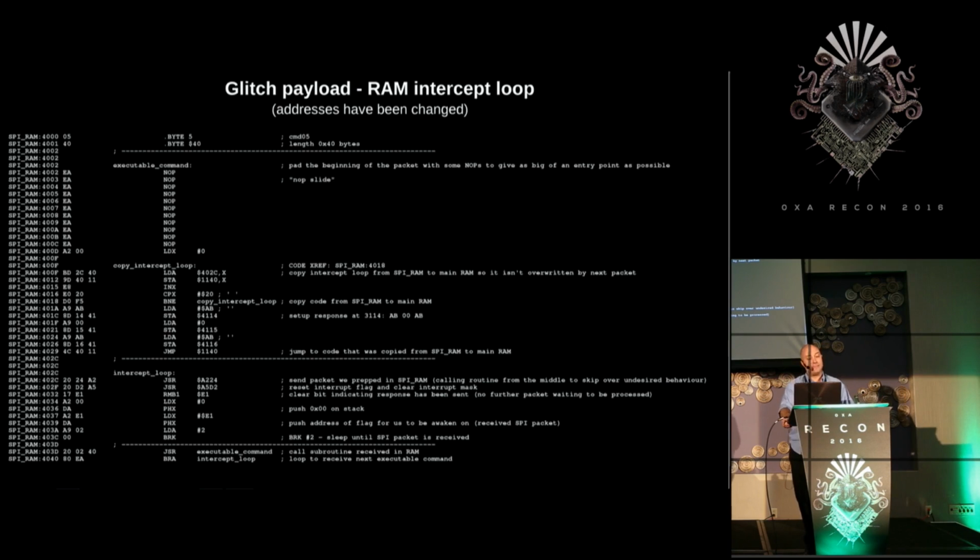Now my goal is to have the ACP execute the code of my choice. Because the 6502 is a von Neumann architecture, all the code and data memories share the same address space. From the software disassembly, I've seen that there doesn't appear to be any kind of paging or MMU features. The software in the ROM is fully self-contained. There is no EEPROM, and the RAM is never used to hold executable code. So there's no jumps into these areas to exploit, and it wasn't really clear at this time if there was anything actually preventing code execution outside of the ROM.